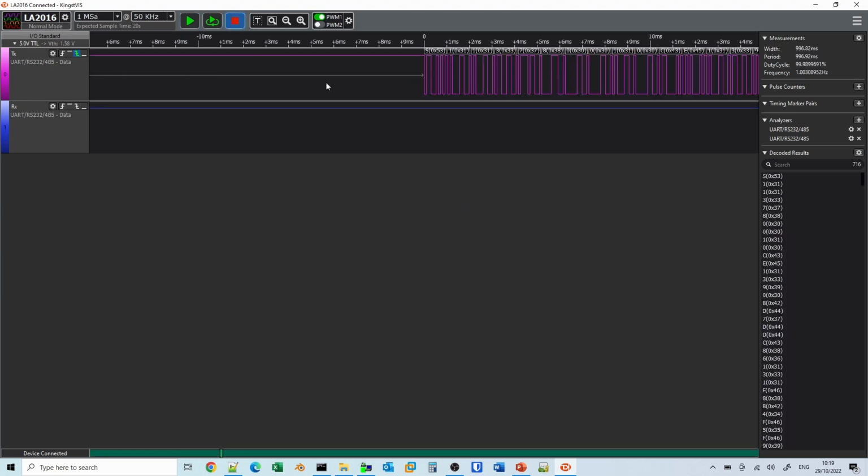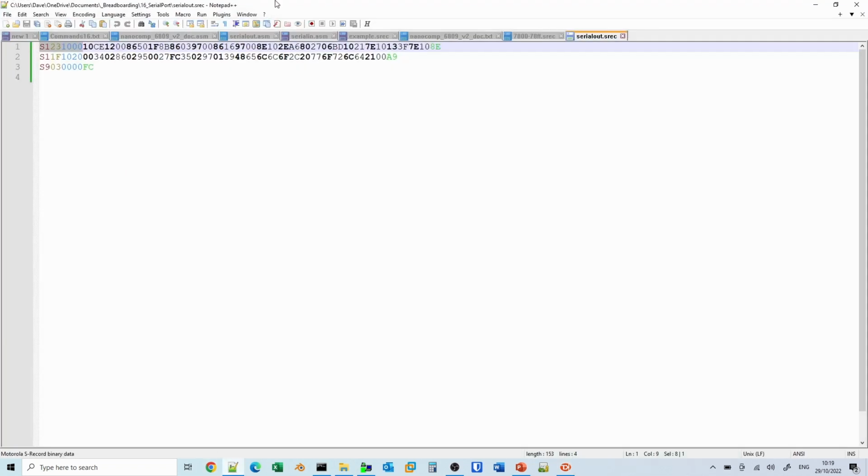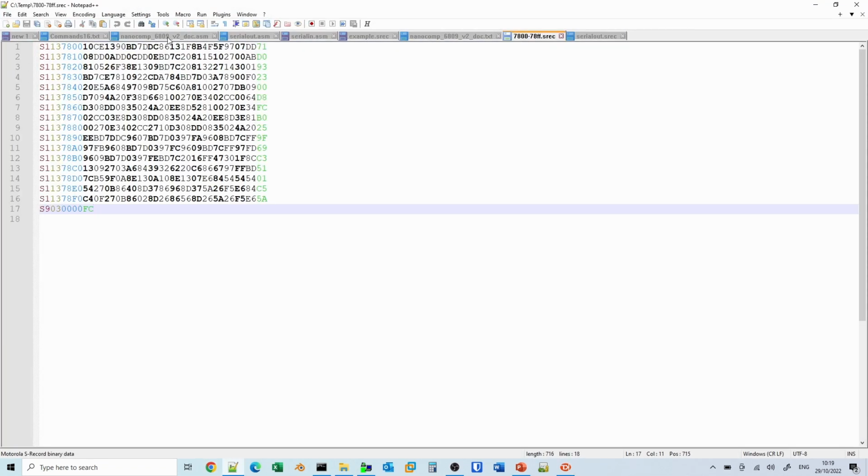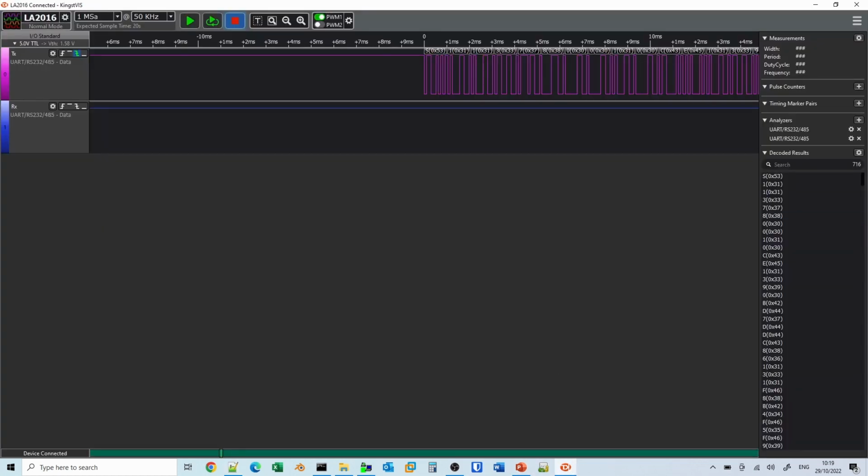We can now see the uploading data, and if you remember, we had this on the screen here. We would expect to see S113 7800 10CE 1390 in this particular case. Let's have a quick look, and we've got 3131, so that's S1, 13 is the length, 7800, 10CE, 1390. So again, that all seems to be working correctly.